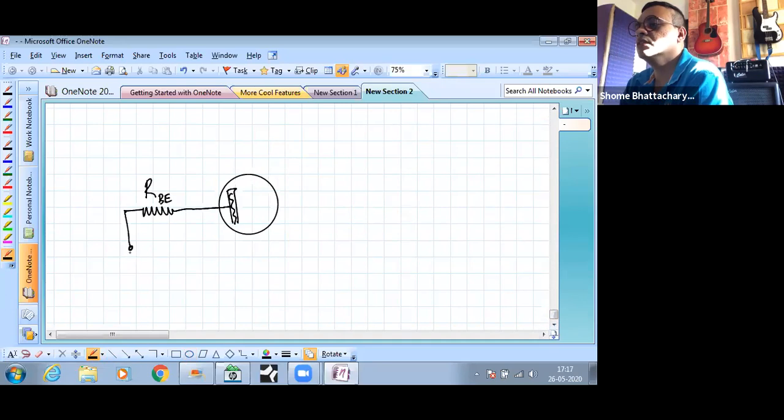Then we have the small signal input voltage which we have connected between the input terminals, and of course there is this DC battery which is connected for the biasing, because we were using what is called an NPN transistor in common emitter configuration.